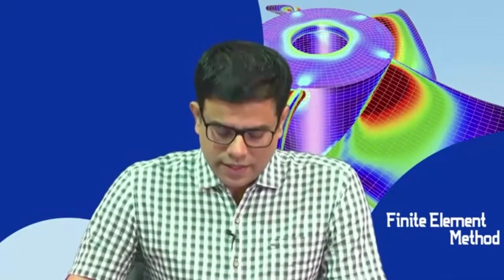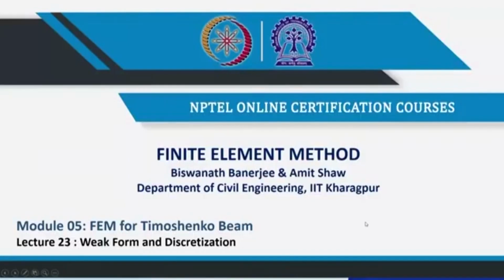Welcome. So, we are discussing finite element method for Timoshenko beam. In the last lecture, we discussed how to derive the governing equation from the energy expression of a shear deformable beam, basically thick beam, not thin beam, that we have learned in earlier lectures, that is Euler-Bernoulli beam is the thin beam where the shear deformation or shear strain is essentially 0. But here the shear strain is actually constant, and we also introduced to consider the quadratic or the parabolic variation of the shear strain, which is coming from the equilibrium equation that actually is modified using the shear correction factor.